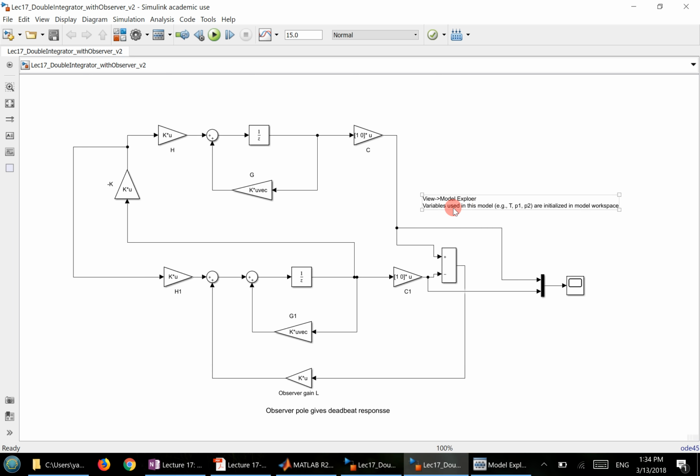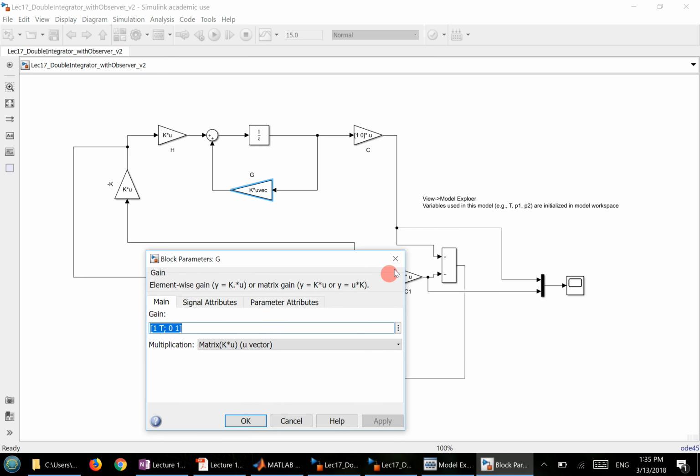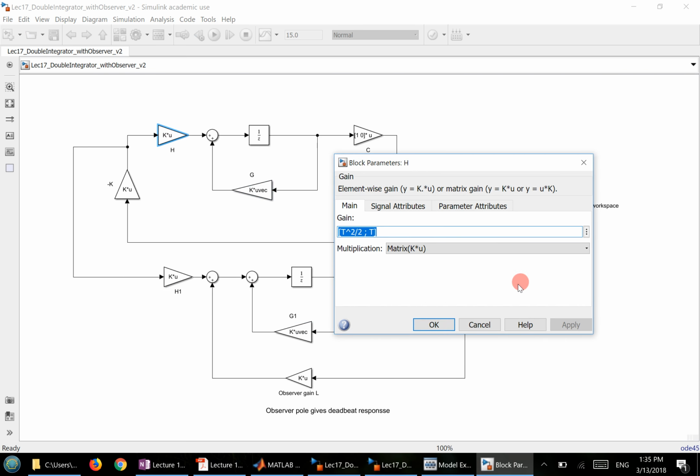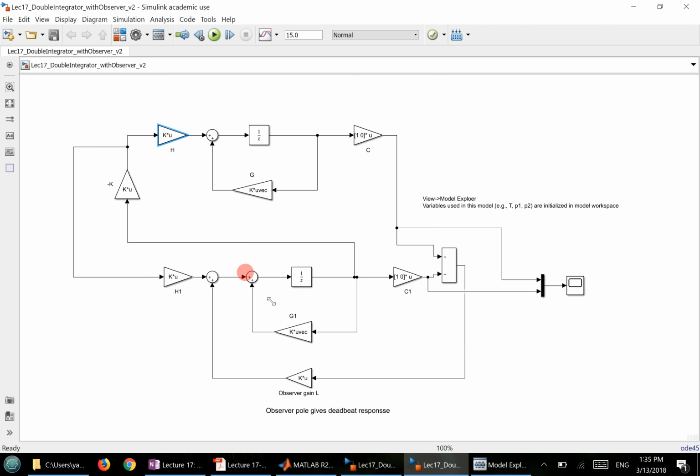Yes. In one of these sample questions, you asked us to run the observer manually. We just need to add values in the middle. That's right, you need to edit the G matrix, and add to the H matrix, of course. And you also need to calculate the K, the L for that system. But the structure is the same. So let's take a look at it. This is the response here.